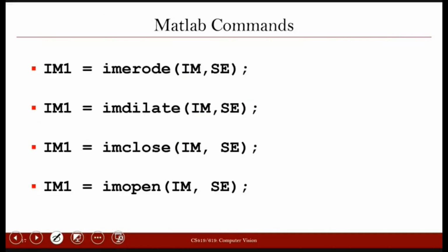These are the available MATLAB commands. You can try them. For eroding the image, you can use imerode. Similarly, for dilation, you can use imdilate. For the closing operation, you can use imclose, and for the opening operation, you can use imopen. As we know from the definitions we have seen, you need the image where the operation is to be performed and the structuring element.